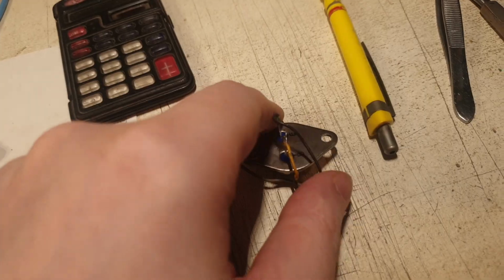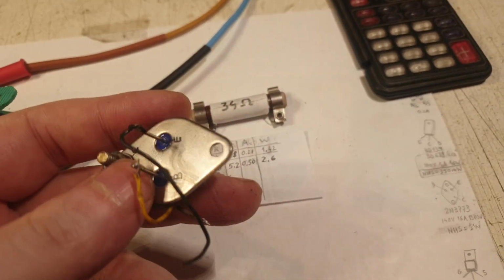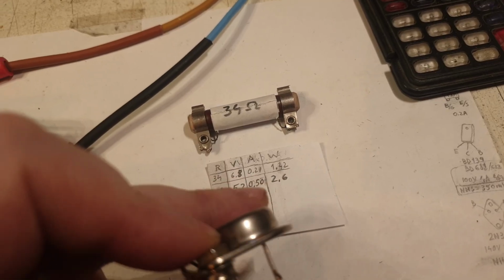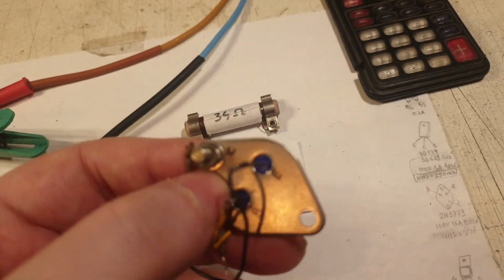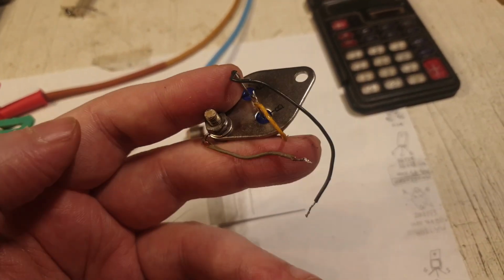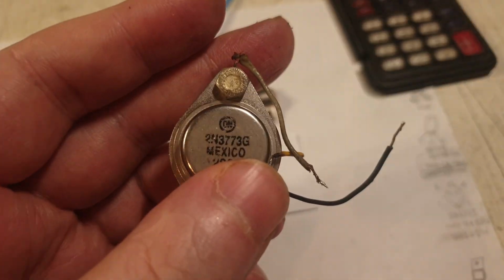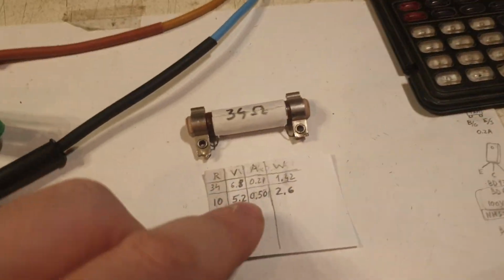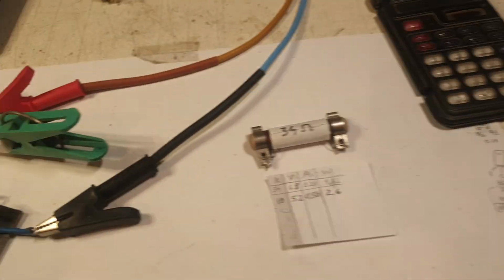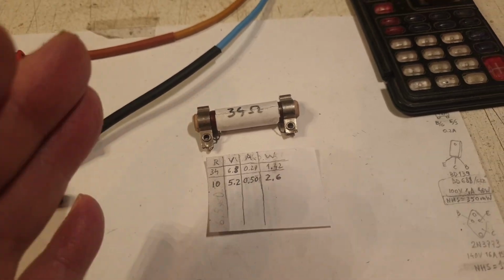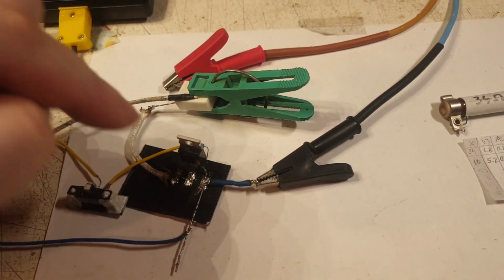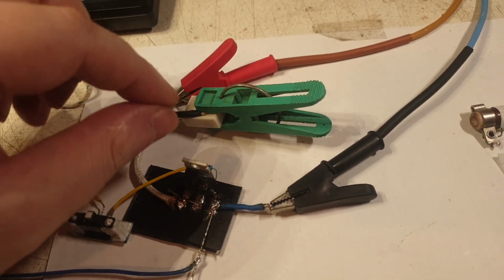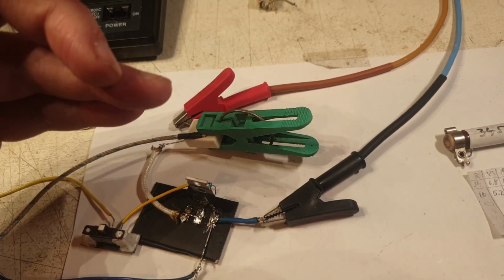remember this guy, when I tested it and I got only one single watt, exactly 1 watt, with like 60 or 80 degrees Celsius over it. I don't remember the temperature. This is an NPN BJT, its name is 2N3773. It barely conducts anything and it heated up like crazy, while this is ambient cold, letting all the power drop over the resistor, and the resistor is getting all the power.